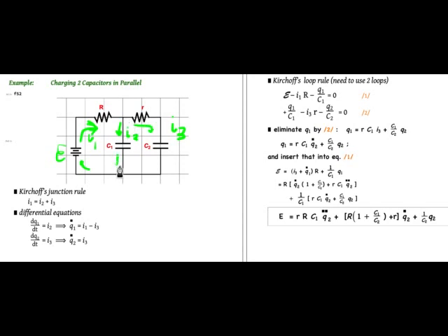Now here again, there'll be a current I2. Any current that goes into a capacitor, an equal amount of current must come out so that the capacitor doesn't become charged. Of course, the charge is separated, so we'll have a charge separation here. And let me use a different color. For the charge separation, we'll call the charge on the upper plate Q1. And then the charge on the lower plate is negative Q1.